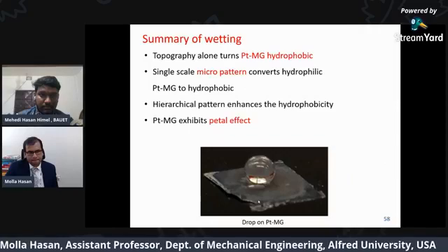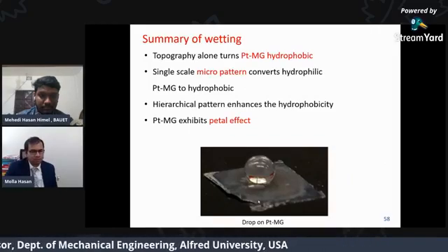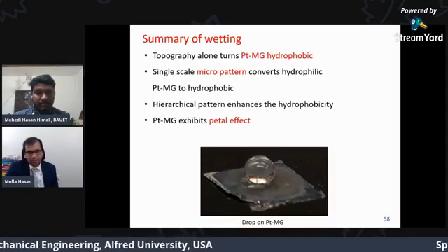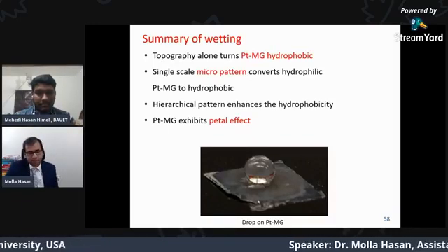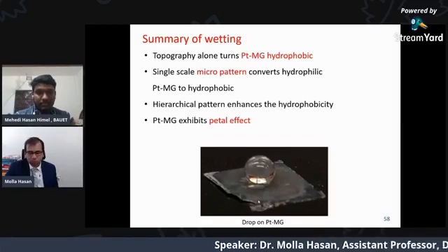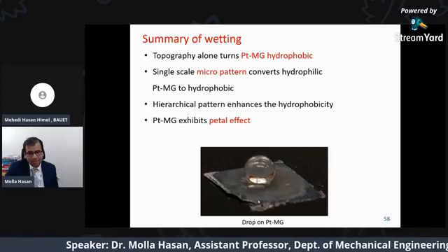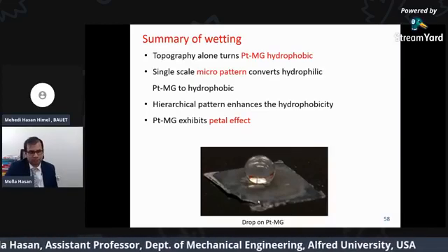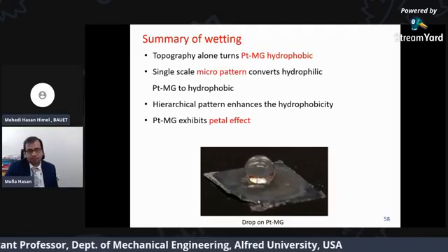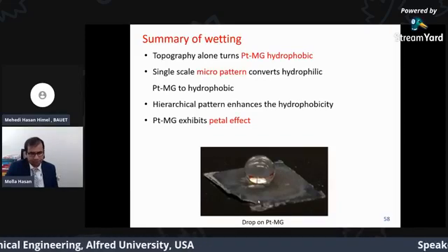Now, this is the summary of this wetting study. The topography alone turns PTMG hydrophobic, and a single-scale micropattern converts hydrophilic platinum metallic glass to hydrophobic, and the hierarchical or multi-tier pattern actually enhances the superhydrophobicity, and the platinum-based metallic glass shows the petal effect.